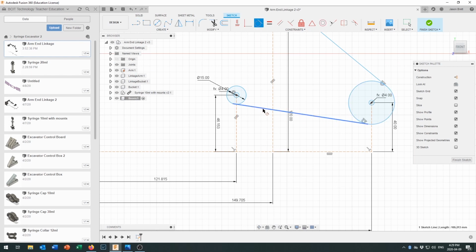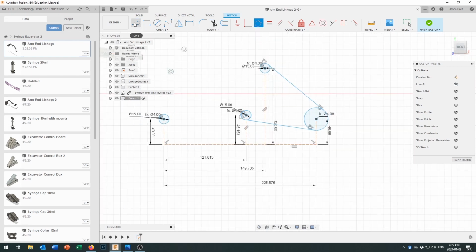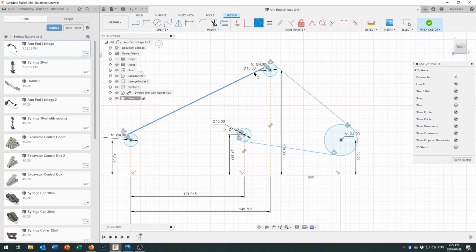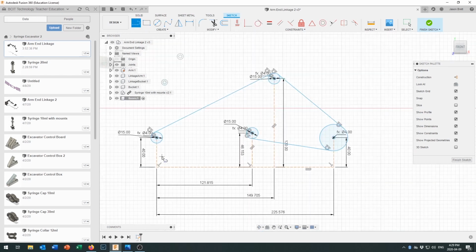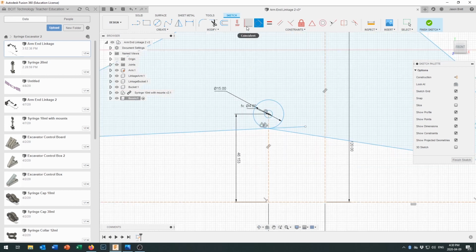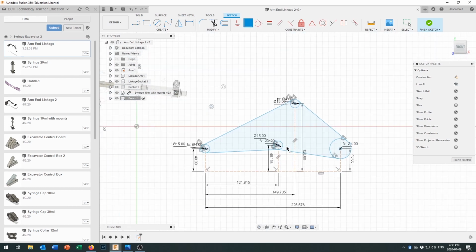Now, one of the things I'm being very careful to do when I apply that is to not implicitly apply any other constraints by where I click on the circle. You sometimes have to go back and take a look at your constraints, and if it's not letting you get nice tangent lines in there, just put it off in outer space somewhere and then tell it to make it tangent, and then down at the end right here, come along and make that coincident with the circle. And that can get you to the spot that you want on the circle.